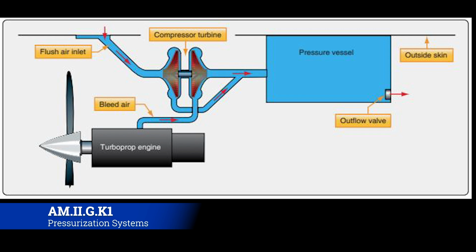So it's the trade-off with the turbine approach to pressurization. One, you could have it cheap and simple, but then you're not going to be able to pressurize as well or as big an area. You're not going to be able to fly as many people or as far or as high. Or you can have a compressor on there and ramp up the cost of the system, but you're able to do a whole lot more with it. That's a dynamic that surrounds business aviation: you're always doing a spreadsheet analysis of how far am I flying, how many people am I flying, and what's my budget. That puts you in a category of what aircraft you actually need, and these are some of the things that change that aircraft based on the way it operates and the way it ramps up the cost.